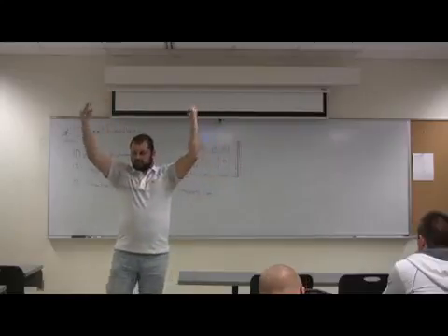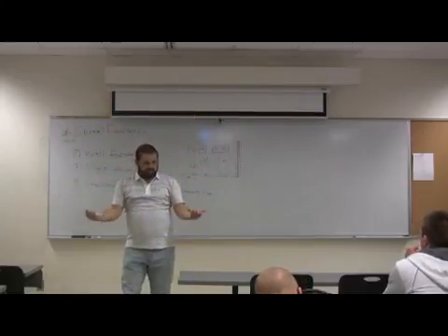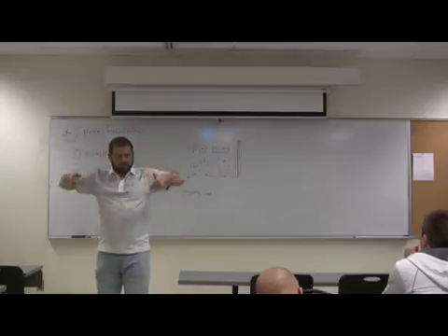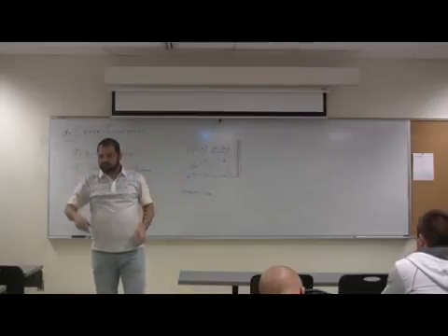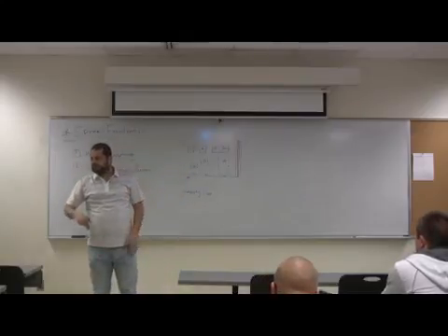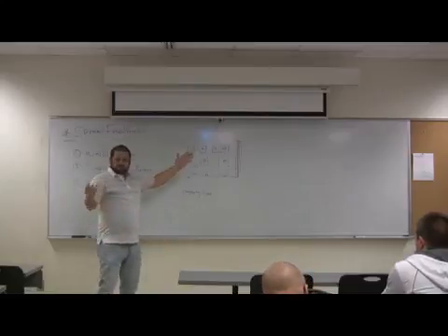And the distributed load on that foundation is the resistance from the soil. If you flip the footing, it becomes like a slab. If you flip the slab, it becomes like a footing. Okay? So that's what's called mat foundation.